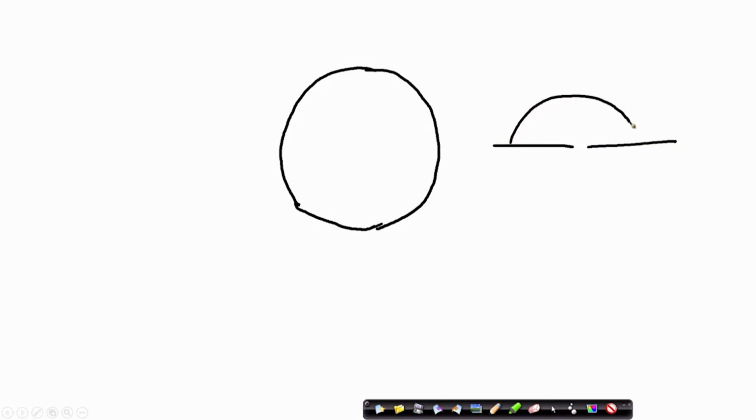So, the modes of a spherical resonator. Actually, for the analysis the dielectric resonator is considered spherical, because this is the ground plane, this is the slot. So, if you consider a single layer, this is the ground plane. The dielectric resonator is reflected in the ground plane, so it becomes a full sphere. Okay. So, it is reflected in the ground plane using image theory.